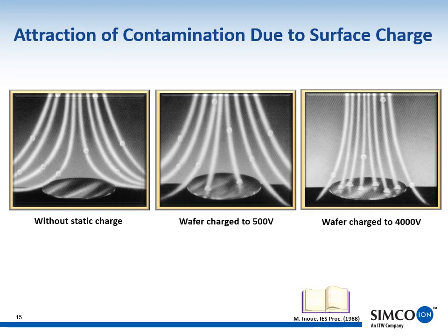Let's move into contamination concerns. This slide summarizes a paper published back in 1988. The study found that when a wafer had charge on it, it collected significantly more contamination than one that had no charge. The greater the voltage or charge on the wafer, the more contamination was collected.